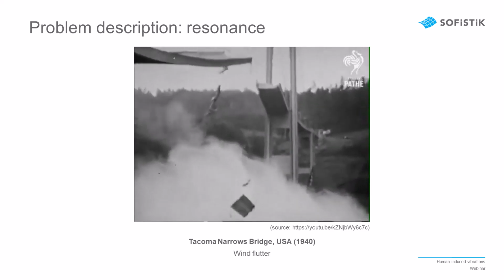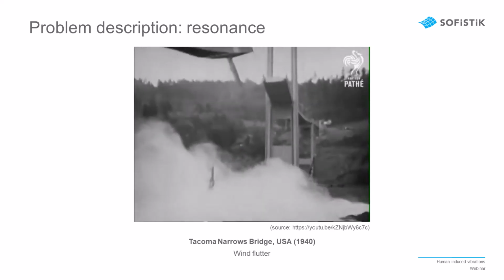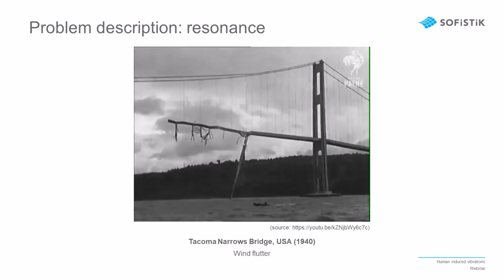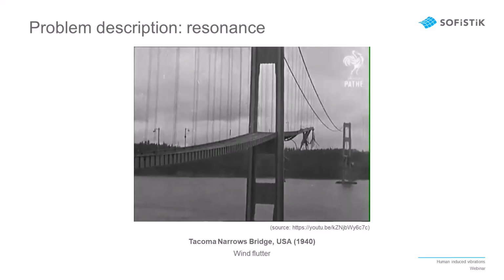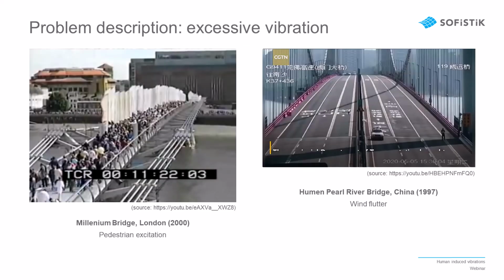As discussed, the resonance amplitude and thus resulting strains depend on multiple factors and really rarely lead to structural failure and collapse. On the other hand, they can very easily lead to excessive vibration, as happened in these two highly publicized cases. The economics of modern design and construction dictates that the structural design is to be as efficient in terms of material volume as possible.